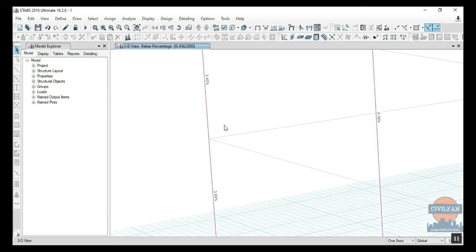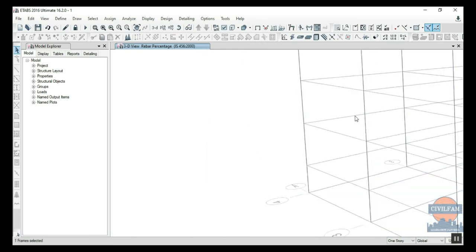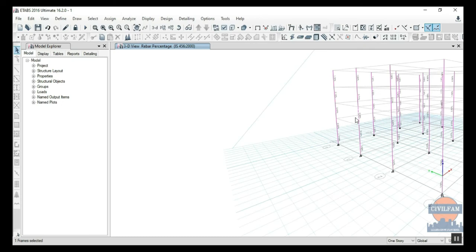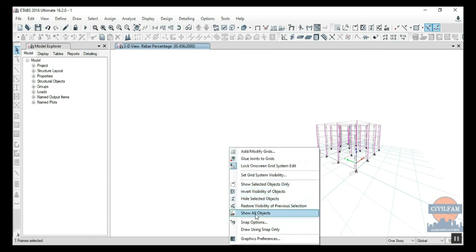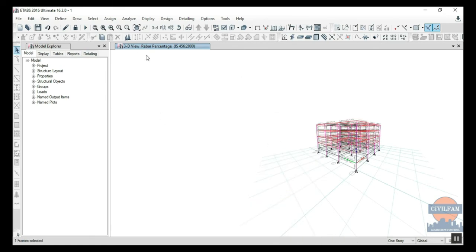Okay, 3.9, we have got 3.93, 3.40 is almost touching. Here see we have got 4.39. This particular column can be cast on the field, but it will be very difficult because concreting and vibrating that concrete becomes very difficult. So how to make these columns and beams safe, everything I'll teach you in the next part. For now, as all the beams have failed, let's make them safe.